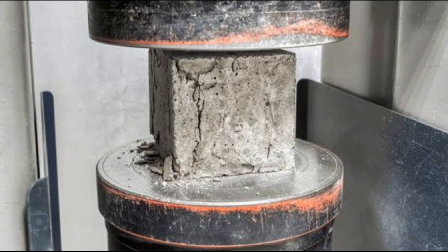To assess the development of concrete strength over time, the cubes are placed in a compression testing machine and force is applied until the cube fails, with the maximum force applied being recorded as the cube strength. Then, the compressive strength of the material is calculated by dividing the maximum load at failure by the cross sectional area of the specimen's face that was subjected to the load, and the result is expressed in units of force per unit area.